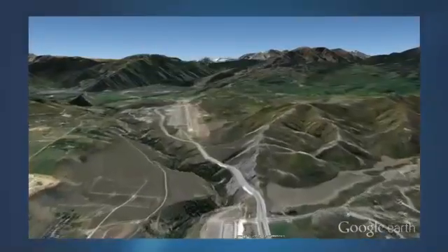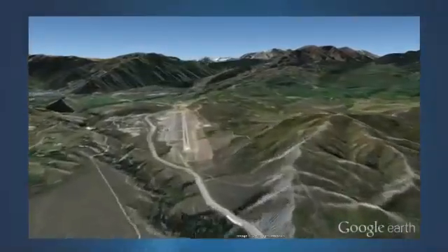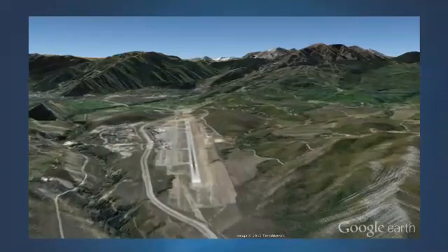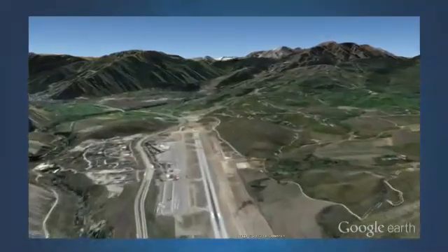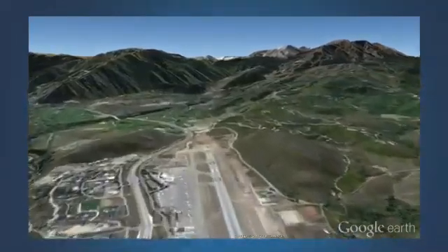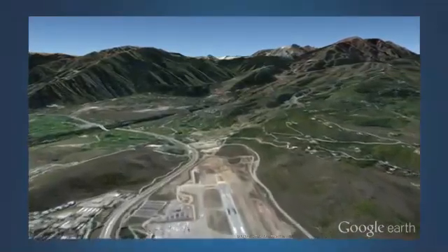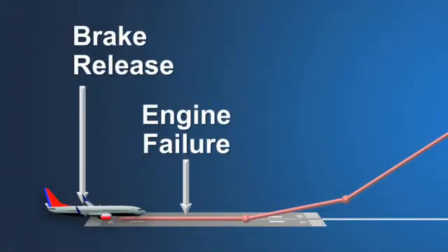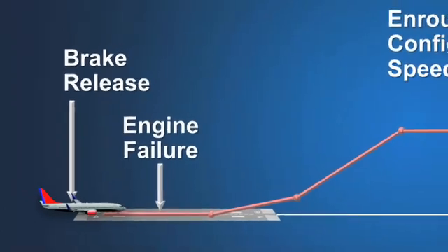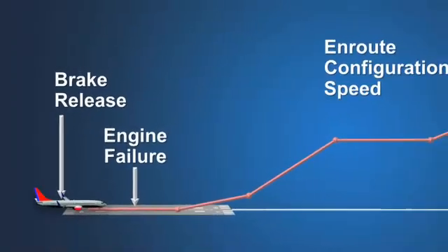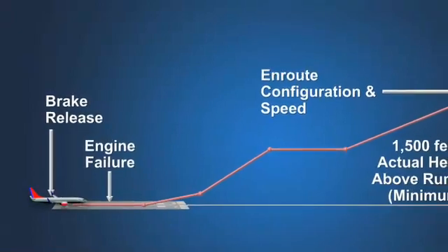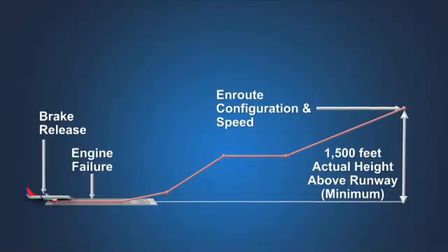This flight crew has accomplished a thorough review of the performance challenges affecting their planned departure from Aspen. Now let's take a moment to examine the challenge of takeoff obstacle clearance and avoidance planning when departing Aspen. A review of the certification rules regarding the takeoff path is a good place to begin our discussion. The certification rules define a takeoff path or vertical profile that is used to establish both the takeoff climb limit weight and the takeoff flight path for determining the takeoff obstacle limit weight.